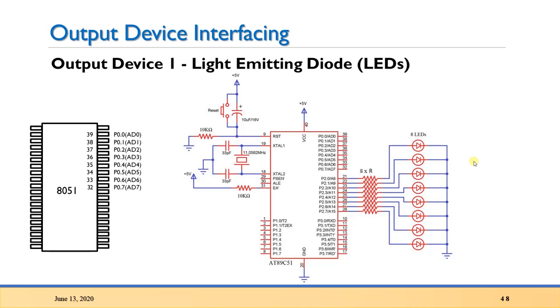This is how the circuitry is shown, and then the other associated circuitry is related to the crystal, that is the clock generator, and then the second part is the reset pin, which is connected to the external circuitry, so that externally we can reset the microcontroller.